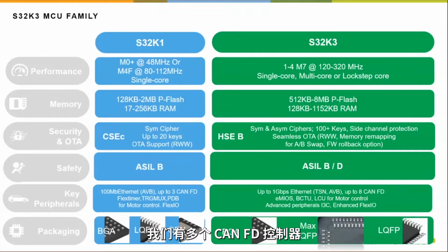There are multiple CAN-FD controllers, of course, and a very rich analog and timing IP set, in particular for motor control. We also will include I3C, the extended version of I2C, in future devices. And we keep the FlexIO module from the S32K1 family as well. That's a nice little peripheral that offers some flexibility in terms of emulating serial communication interfaces through programmable logic with its own DMA. All of that IP and more is then packaged in LQFP, BGA, and a new technology called